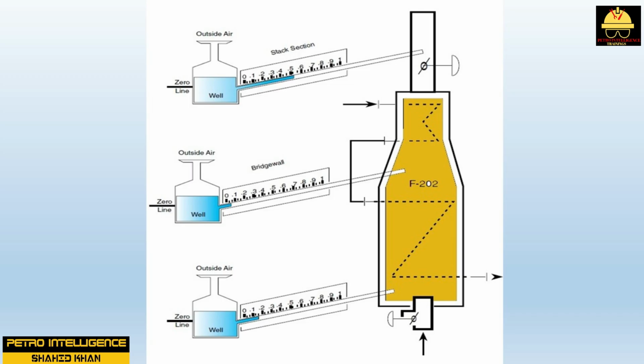Excess airflow will decrease furnace temperatures around the burners and force the automatic controls to increase natural gas flow rates to the burner, wasting money. As hot combustion gases rise, cooler air is entrained, causing the temperature to decrease. Excess air enhances this process. When excess air is increased to the burner through the primary and secondary air registers, a temperature shift occurs as heat is moved away from the burners.